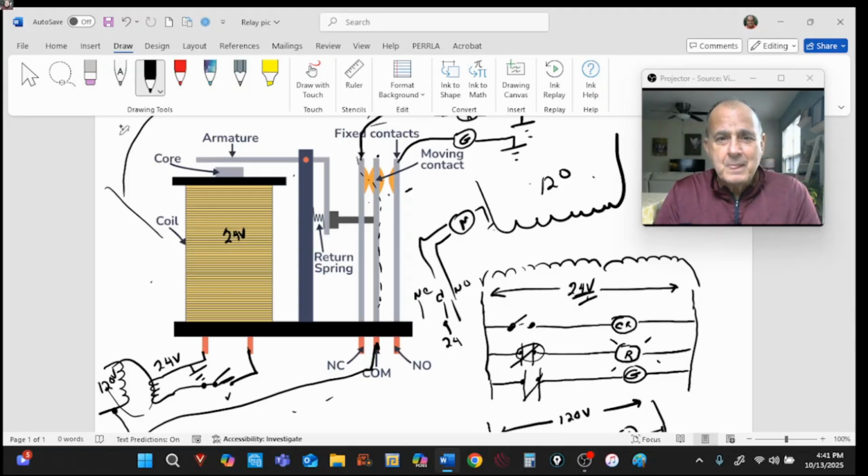So hopefully that gives you a good understanding of how to turn a wiring diagram into relay logic. And this is what electricians understand. And this, by the way, as we mentioned before, is what PLC programming goes by. It's called ladder logic programming. So it's kind of the same principle, because this is what electricians understand. And typically these are read from left to right and from top to bottom, like so.